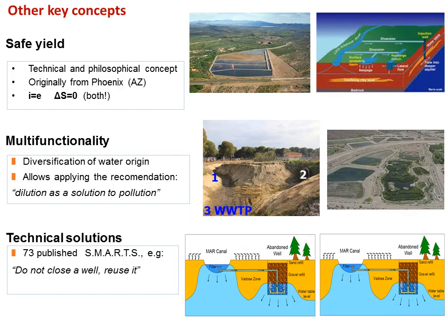Some other key concepts are the safe yield, a technical and philosophical concept originally from Finland, in which the inflow is exactly the same as the outflow. Multifunctionality is also important, or diversification of water origin, which allows applying the recommendation dilution as a solution to pollution, meaning that you can combine different waters of different qualities in different doses.